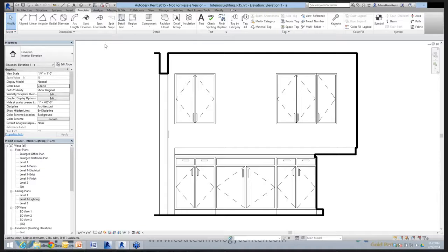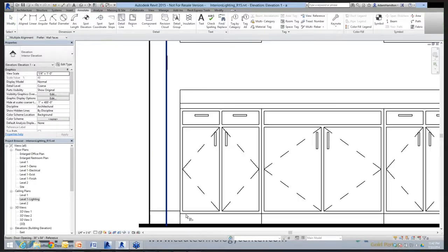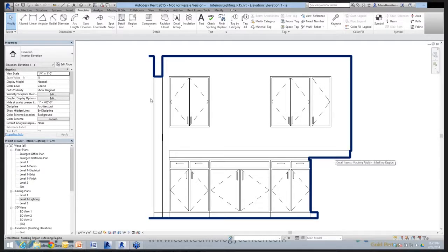That'll slow down the model, especially if it's in an area that you're not going to be creating a perspective for anyway. What you can do is in your interior elevations, you can punch up the model using the default Revit content, or default objects in the background, utilizing line work as well. And so what I'll come back in and do is choose some of these elements and align those pieces to the model. And so you can have line work, you can have masking regions, and even filled regions, so hatch patterns, with the model in the background.